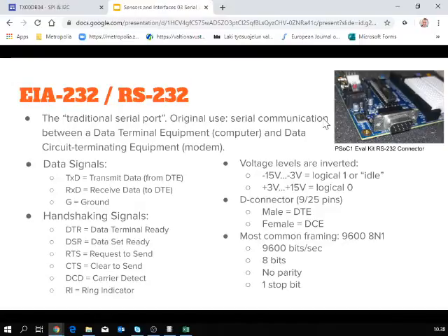But there was already a need for communication, so serial line communication was selected for two good reasons. Simplicity of wiring, since the most painstaking operation in communication is always connecting the wires. That's why in most cases you need only a pair of wires for data transfer, just like these asynchronous digital subscriber lines, ADSL, if you have that kind of old technology at home.